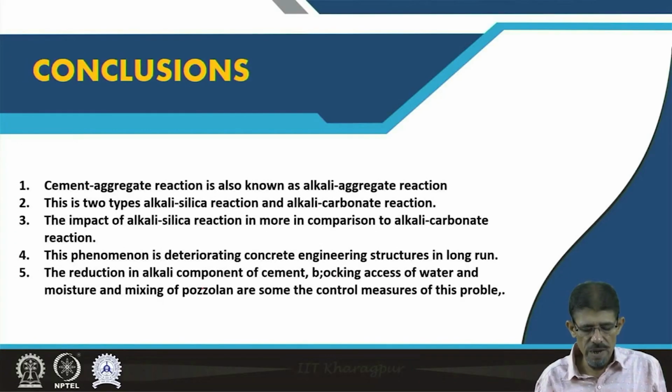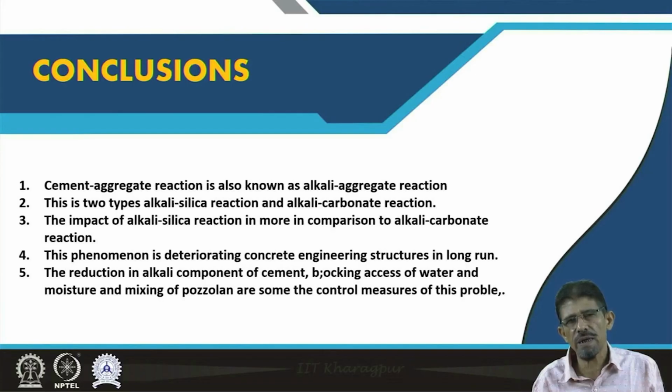Friends, if we try to conclude our discussion, then we can say that the cement aggregate reaction is also known as alkali aggregate reaction, because here alkali participates in such reaction. It has two types: alkali silica reaction, in short ASR, and alkali carbonate reaction, in short ACR.